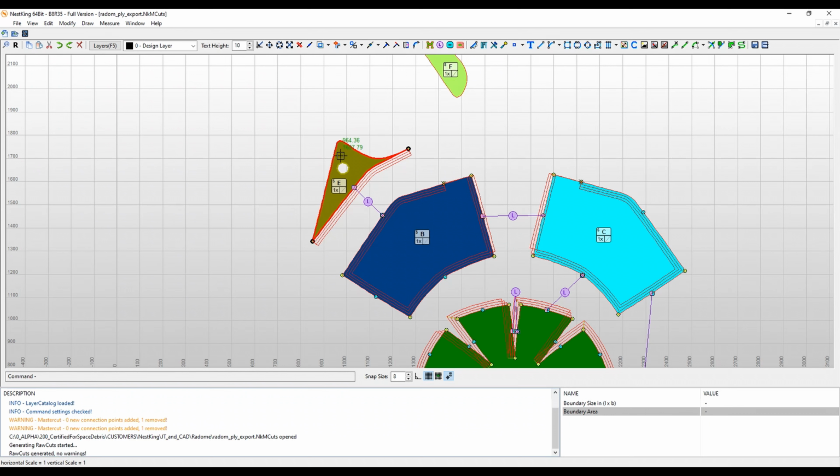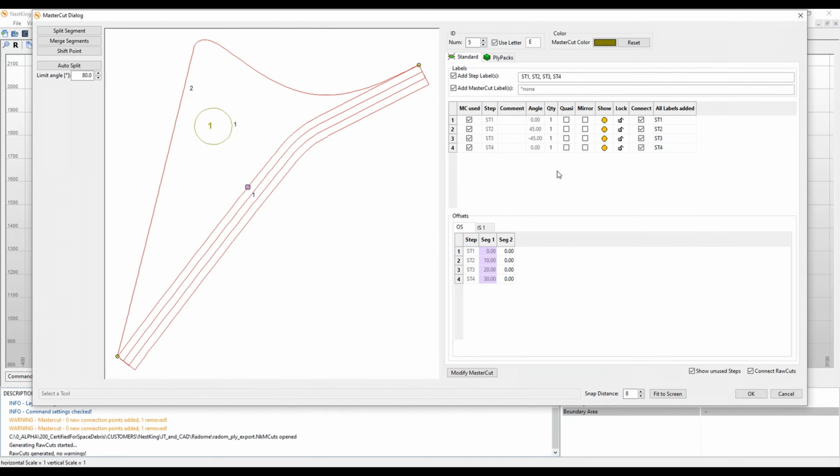You could either model or take this, copy paste, and then link and so on. Would also work, but it's much easier just to double click and say you want to mirror all of them, and it will automatically create a duplicate of this, which is mirrored. You could also increase the quantity if you had more of these and they were same, also from the orientation, then you could duplicate them and have it either mirrored or just simply duplicated.